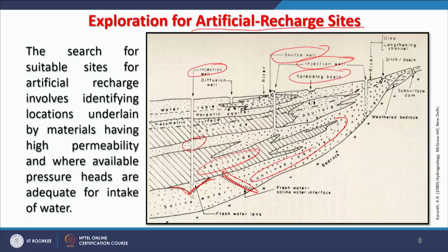And the cheapest and easiest way of doing artificial recharge in unconfined aquifer conditions is locating sites which are only on the surface. So, small check dams, trenches and other structures will delay the surface runoff, and then your unconfined aquifers can be recharged. Let me take an example from weathered, fractured, unconfined granitic terrain, or any such terrain where only the top few meters, maybe 5-6 meters, have water and the rest does not, because you have consolidated rocks.